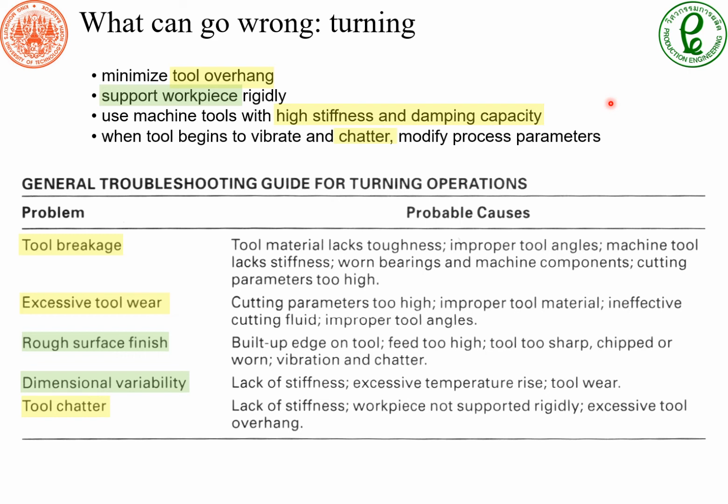So the machine structure is very important to control the vibration of the machine. And the vibration creates problems with the surface quality of the workpiece if the machine is not stiff enough. In an uncontrolled or poorly designed process, the cutting tool can start to vibrate and have chatter, where the tool can break, the workpiece material can also break, causing the process to be interrupted.